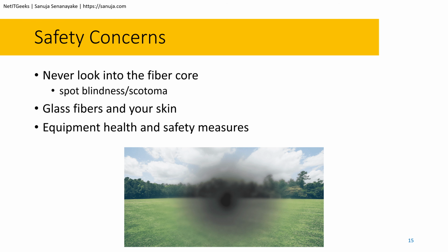So this is a really important slide, even though it doesn't have much information, because I'm going to quickly give you the most important thing that you need to remember when working with fiber. You should never ever look into the fiber core when you work with fiber optic cables. It doesn't matter if your manager, your supervisor, your team leader, or your senior people tell you that the cable is disconnected. You should never ever look into the cable. Even if your managers and supervisors tell you to look into it, do not do it, refuse it.